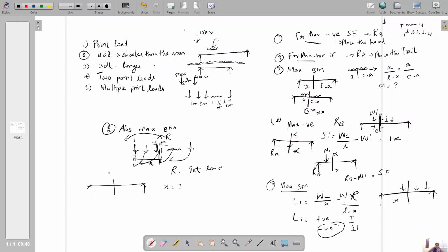We need not place the resultant for further calculation. We only need to place the critical load at the half distance evaluated from this calculation. If you place this load, the other loads are automatically placed because the distances between them are fixed.